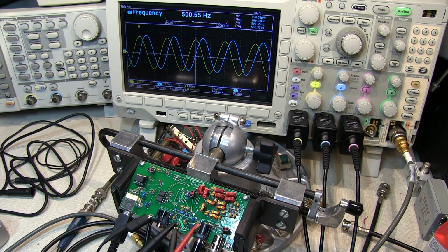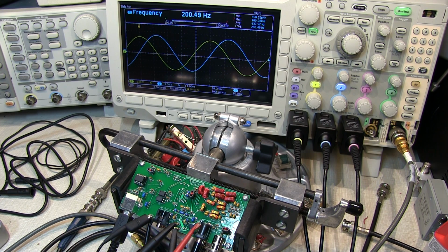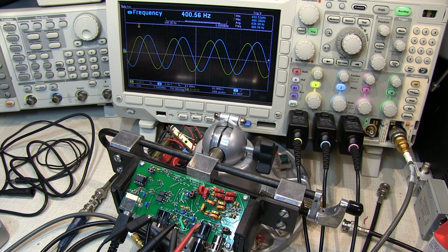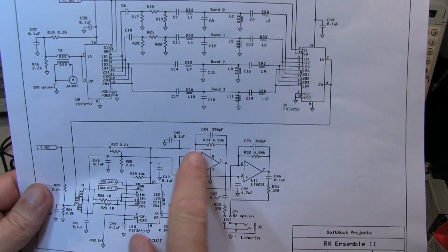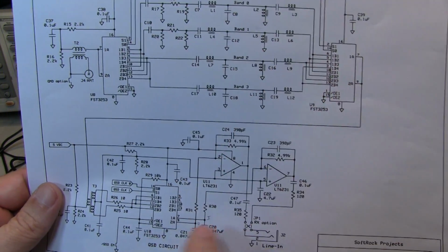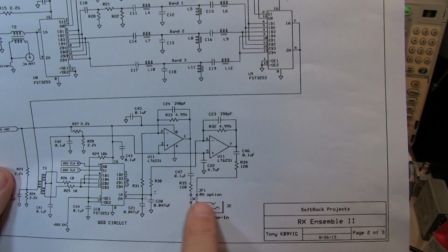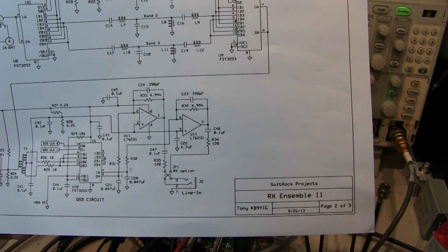If I adjust the frequency of my local oscillator in the receiver up and down, I can see that those signals maintain their 90 degree phase offset relationship, but they stay at that same frequency. Again, identical signals, but 90 degrees out of phase. So that tells us that the Quadrature sampling detector or Quadrature mixer is working, and those low-pass filters are working as well, getting rid of all those clock feed-throughs and other high-frequency artifacts. So that creates these effectively wideband baseband signals that go into the sound card.